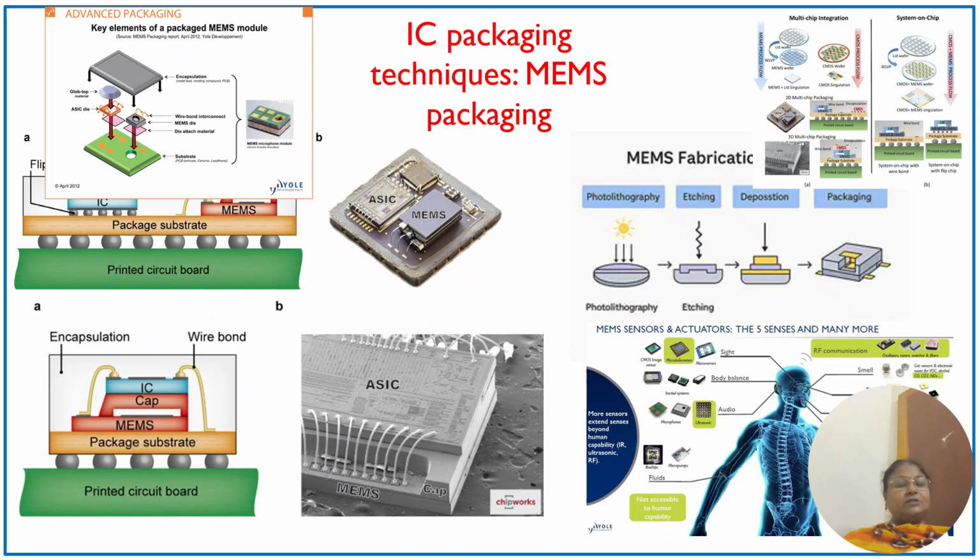Now look into this where a hybrid module is also possible. We have a PCB board, and then we have these ball grids, which are going to establish the connection between the packaging substrate and the printed circuit board. Packaging substrate is nothing. It's going to be either with semiconductor silicon, or it can be with a variety of polymers you can have, or it can be the compounds of silicon also. You can have the substrate.